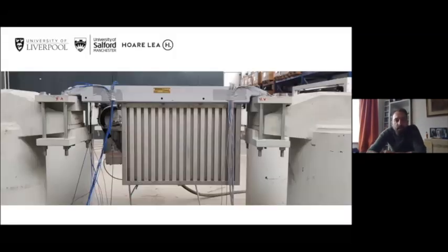First of all, you can see from this piece of equipment, its mounting points are here and here. There's a lot of it that hangs down afterwards because it hangs off the bottom of the train. So you can see that in this case, it would be relatively impractical to mount this to a reception plate unless you had a reception plate with a big hole cut in the middle, which would mean developing a bespoke reception plate for this specific source.